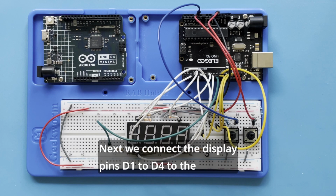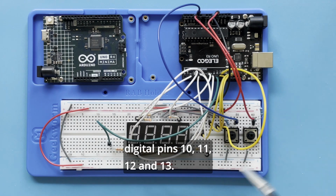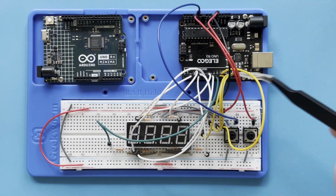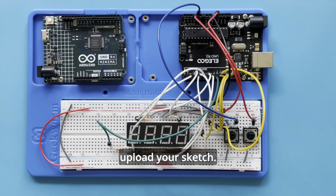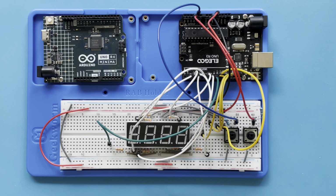Next, we connect the display pins D1 to D4 to the digital pins 10, 11, 12, and 13. We do not recommend the use of the digital pins 0 and 1, as these are used by the Arduino itself to upload your sketch. You can see that these pins are labeled RX and TX, short for receiving and transmitting.